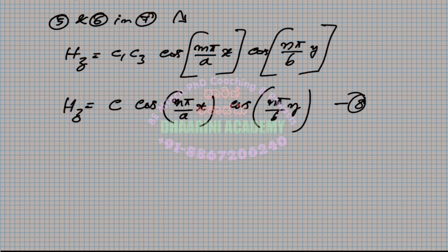Now try to recall what was the step we did after finding out the Ez in case of a TM wave. Perfect, that's the right answer. We are supposed to multiply by the e to the power j omega t term, to take care of time and the axis along which it moves.